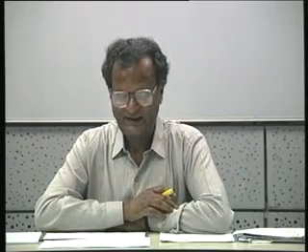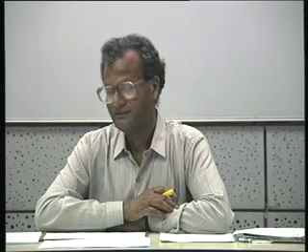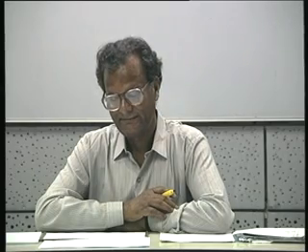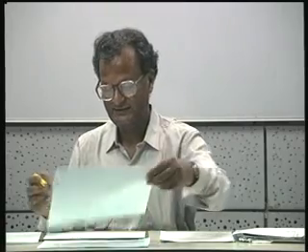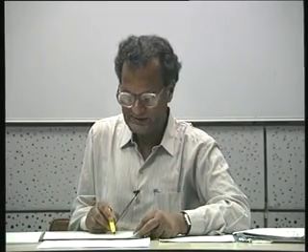And you can try taking y. Expand the lowest power, starting at lowest power. Can we expand the impedance or admittance, or can we do either? It depends on what you started with. In here my z of s was this, and I started with lowest power 6 plus 5s plus s squared in the denominator. Therefore, the quotient is impedance.